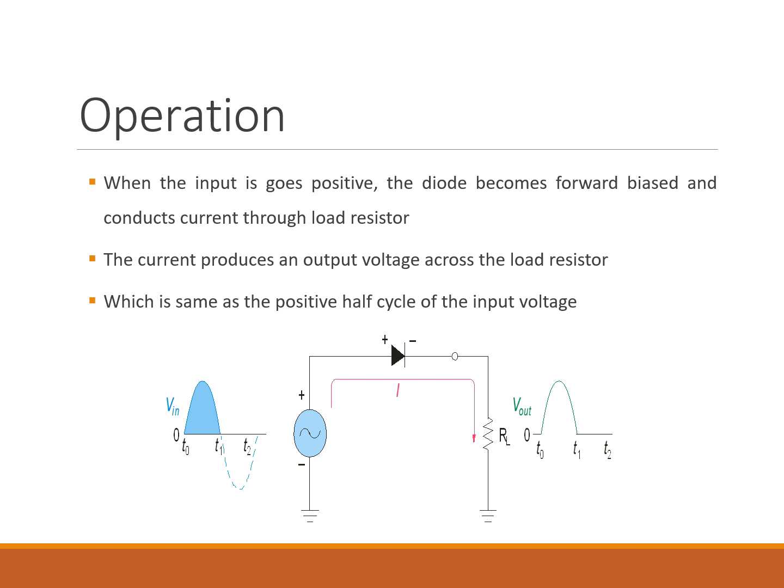And the final output waveform, the result, is going to be a pulsating waveform at the output. Voltage during the positive half cycle, flat zero during the negative half cycle. That's it. And this is your classic half wave DC. So let's recap this whole slide: the diode turns on during the positive input, the diode turns off during the negative input, and the output mimics only the positive half cycle of the AC input.